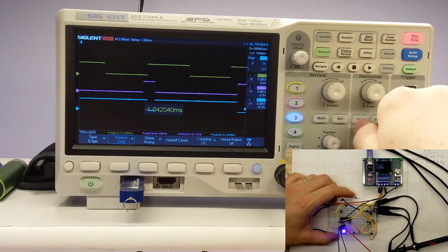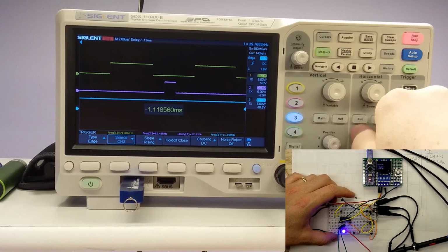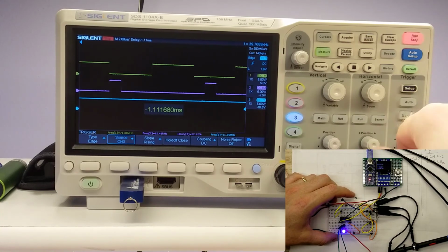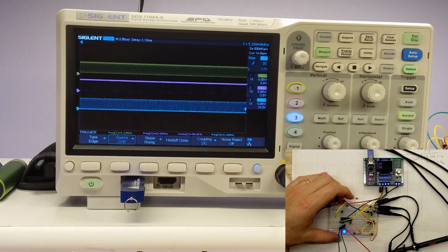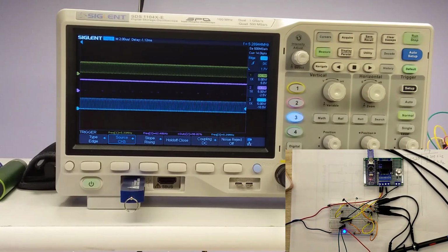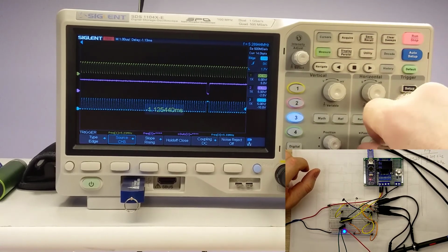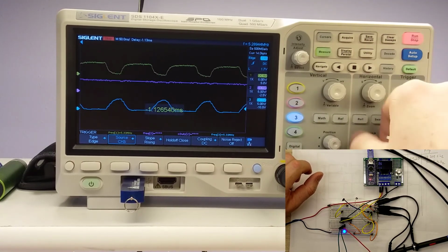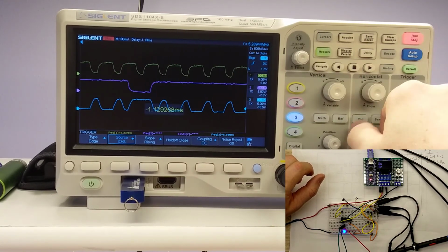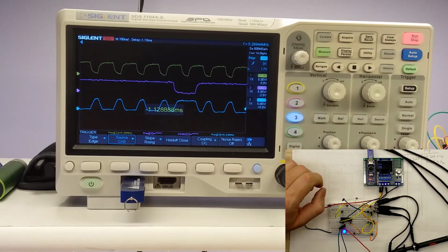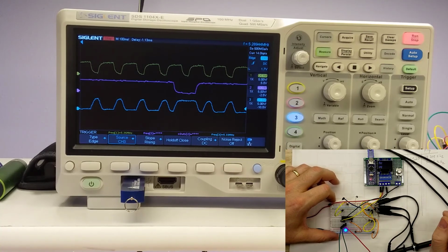So if we zoom in, we can see where both of them are high, it goes low. We've got some variation on that. So I would say that is still perfect at 71 kilohertz. Let's go up to 5 megahertz. So here we are at about 5.3 megahertz, and it looks like it's keeping up just fine, although no real surprise there. Let's pause it. We can zoom in a little bit on a couple of these little anomaly peaks, but I would say that looks really good from just a triggering standpoint. So at 5.3 megahertz, this chip actually did an extremely good job. So I would say this thing is rated for much, much higher than that.